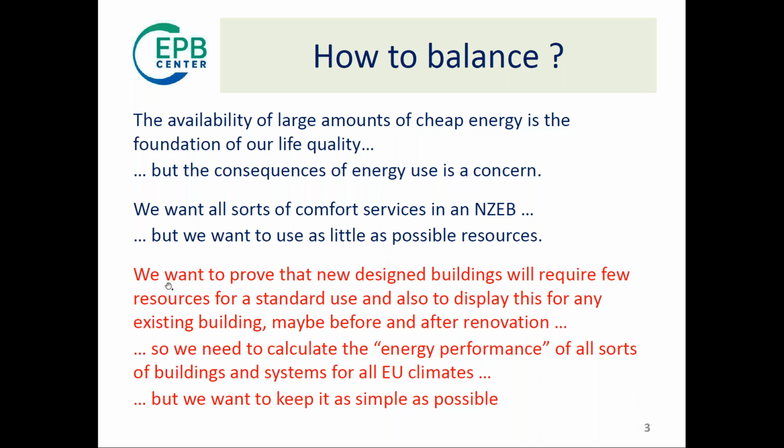And now if we come, for example, to this EN standard, or in general, the standards that you have for legal requirements, we want to prove that newly designed buildings will require few resources for standard use, and also we want to display this for any existing building, to put this information on the market, which is the base of an energy performance certificate. And maybe we want to do this calculation before and after a renovation of the same building. So we need to calculate the so-called energy performance of all sorts of buildings and systems, new, existing. For all European climates, the relevance of heating or cooling changes, or you need both, which is mostly the case when you go to high performance buildings.